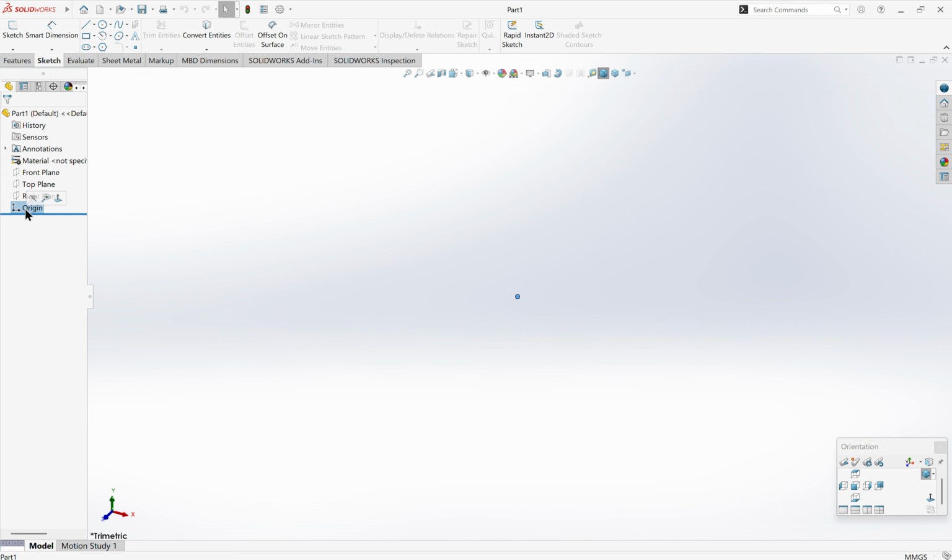The origin is the origin point, the middle, the place that we should start every drawing on. Please start every drawing on it. The first point of your drawing should be on the origin point, so it would be fully defined, or secured and not moved. It can't move anywhere.